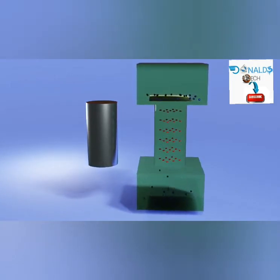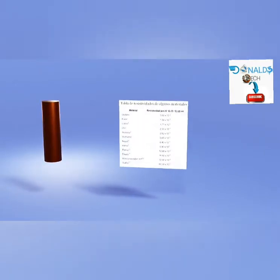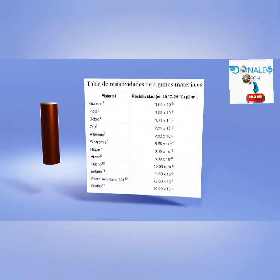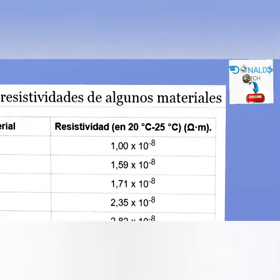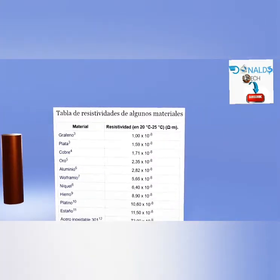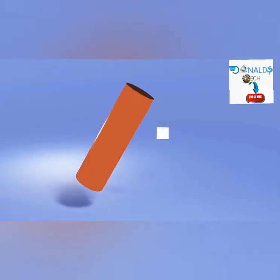Now let's go back to the real version before my computer melts by doing these simulations. Although this formula is usually used for its simplicity, you should know that the temperature can also affect the value of resistance, since the coefficient of resistivity you find in tables like this specifies the temperature at which that value is correct. Although most metals increase their resistivity coefficient while increasing their temperature, this is not true for all